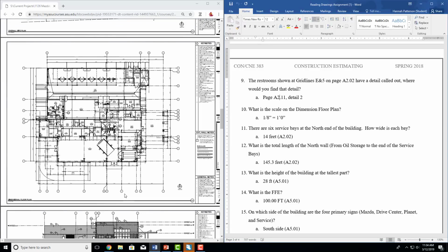So you have to set your scale per what you're looking at. If you're doing takeoffs on a page and you set the scale for the whole page, but different details have different scales, you're going to be very far off. So always check and always verify, because you never know if things have been changed slightly, maybe when you were uploading them to a takeoff software, maybe when you converted them, something like that. Always just check your scale.